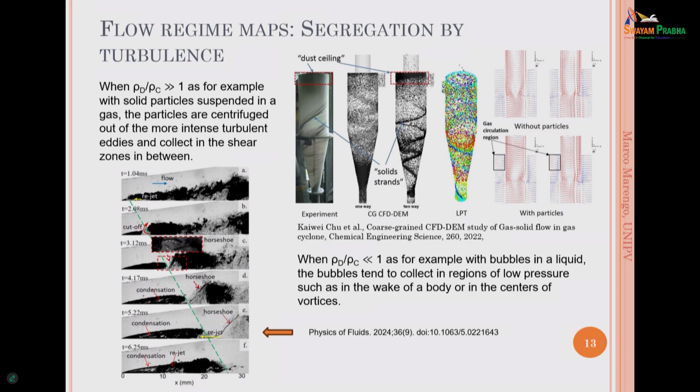So, for example, with cavitation, the formation of the bubbles is changing the characteristic of the motion of the flow. Okay, so these are already quite complex situations to study. They are changing the turbulence level, the turbulence intensity.